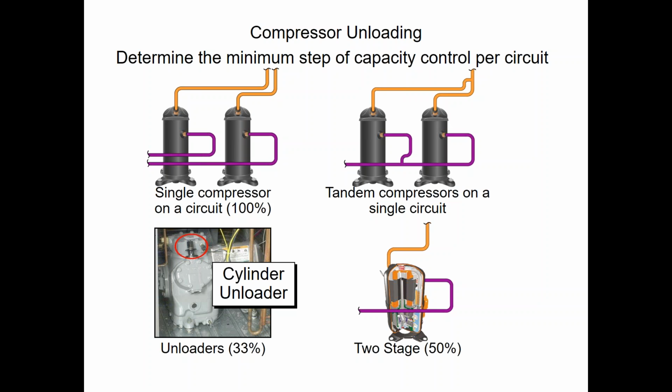And we've got possibly 2 5/8 pipe on this machine, or 3 1/8 pipe, and all of a sudden now we're only running at 10 tons. And now you can start to see, hey, I've got a grossly oversized suction line. So we can handle it in the horizontal areas, but it's the vertical areas that run into trouble on the suction side with oil entrainment and return.